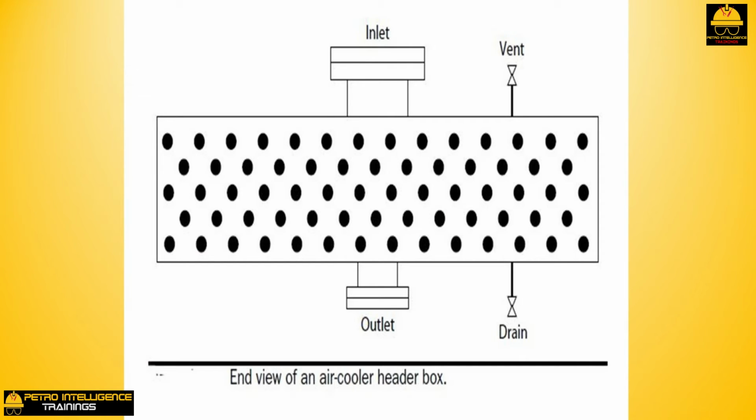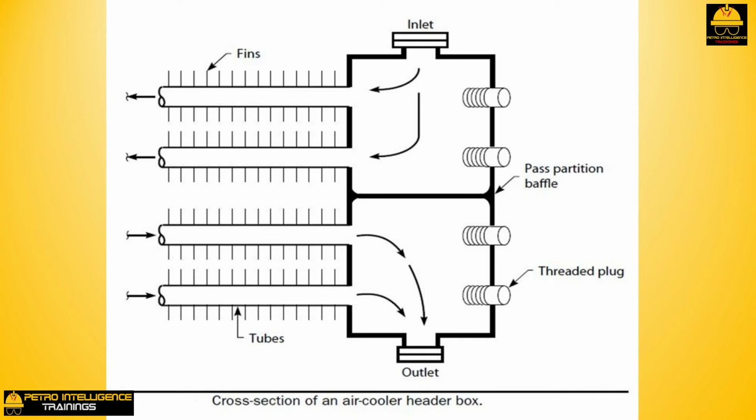It came in a big roll several feet high and about 8 inches wide. The mesh itself was around 2 inches thick and screwed into the inside of the shroud. A simple tool was then bolted onto one blade. After that, the fan was turned by hand to cut a groove into the mesh. It seemed to me that airflow increased by some amount that I did not measure. The operators reported that cooling had been increased.